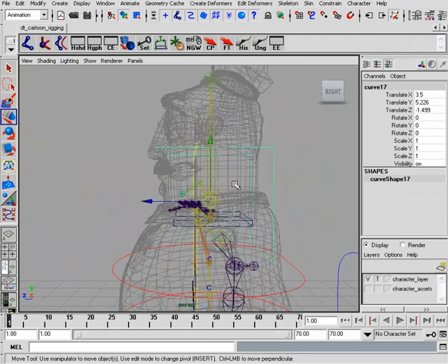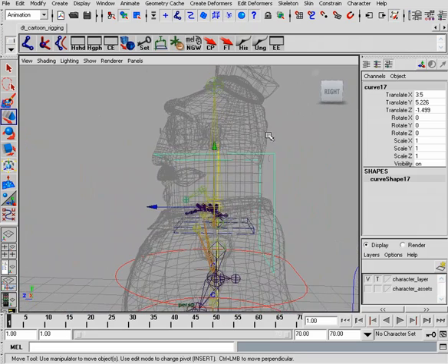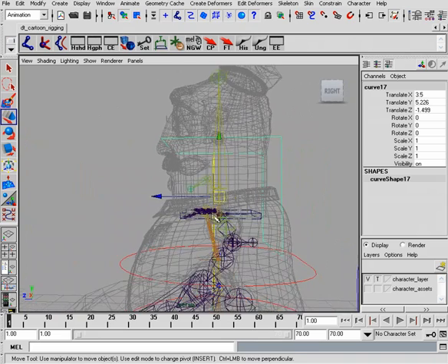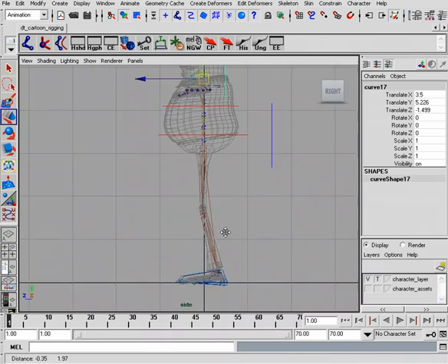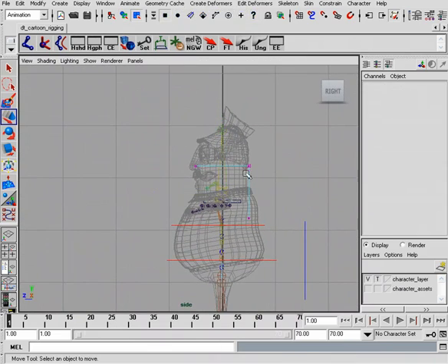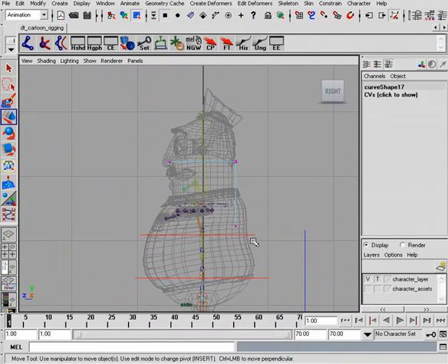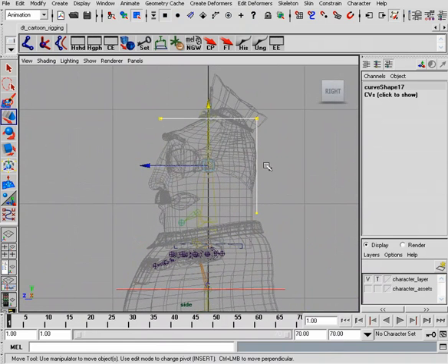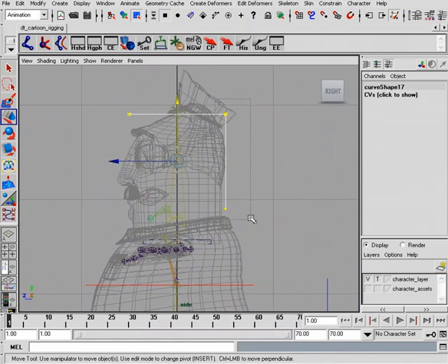Great. And now we're not going to want our head control where it's at, right in the character's back. So let's go ahead and move that. We can go to the side view, go to our verts in component mode, bring up our control, so it looks almost like a little headrest. And we can select these back points, maybe bring them back some more.